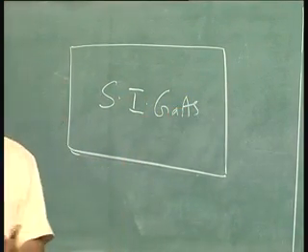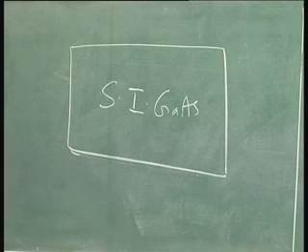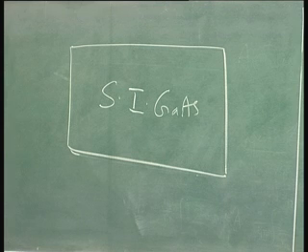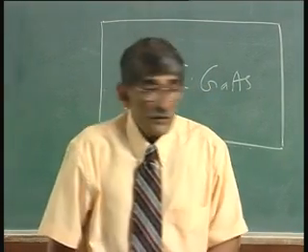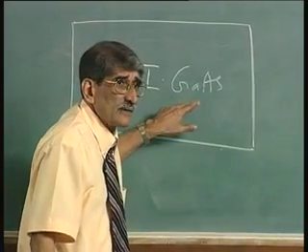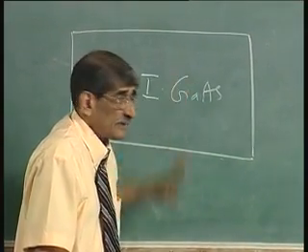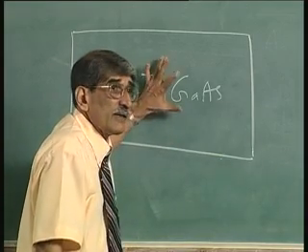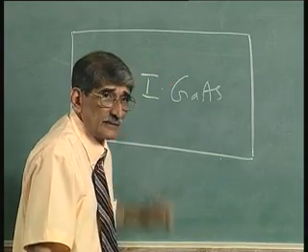If you are making indium phosphide, use a semi-insulating indium phosphide. If you are using gallium nitride, you must look for an insulating substrate, maybe silicon carbide. So, you look for high resistivity materials like that. Since we are focusing on this right now, let us focus on this material itself. First you must be able to get this semi-insulating gallium arsenide material.